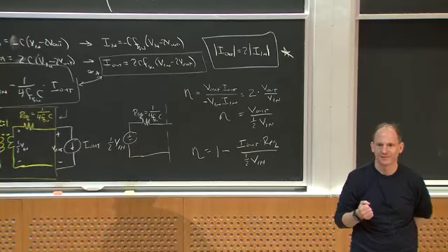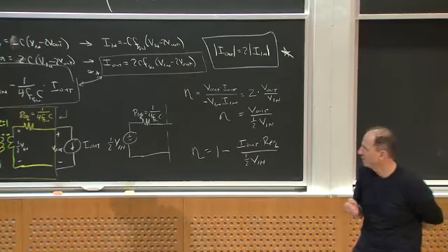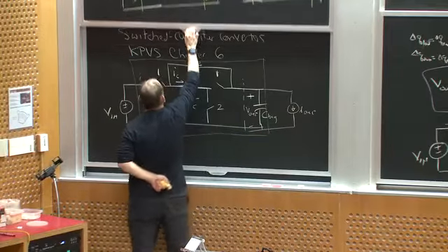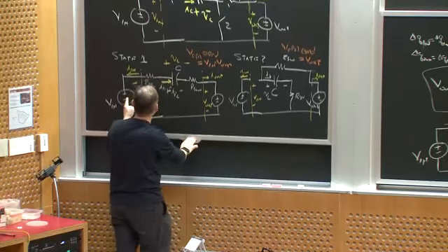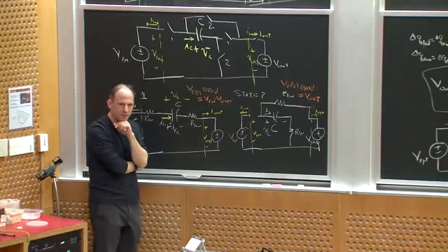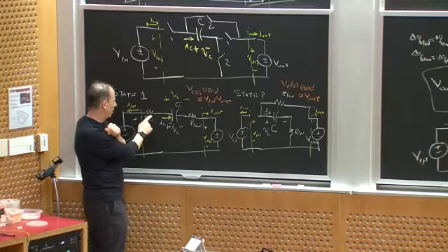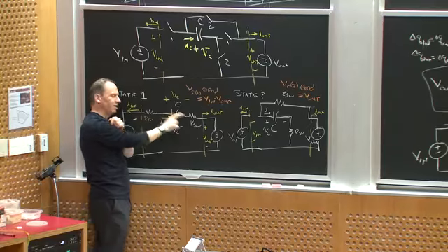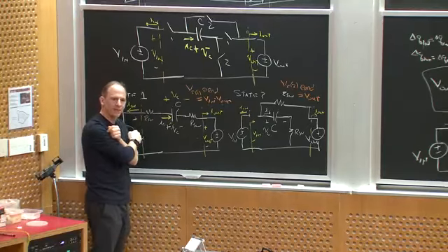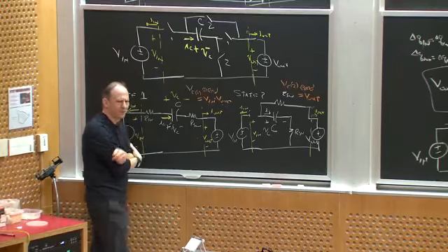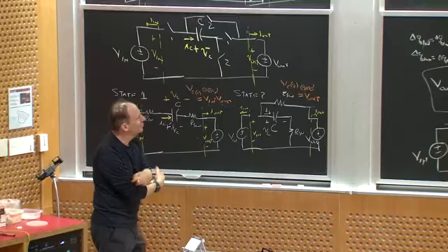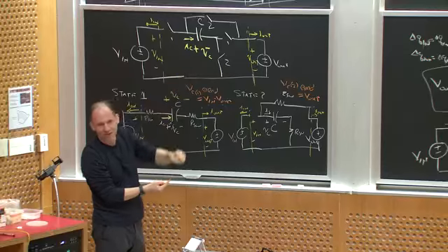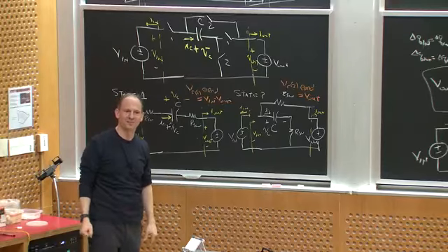Could you say it again, like where the power is being dissipated? The power is being dissipated in any parasitic resistance in the charge and discharge path, okay? So if I turn the switch on, it has some voltage drop across it, or if the capacitor has some parasitic resistance, it loses some energy in that. You say, well, what happens if I make my switch resistance go to 0? Well, all that happens is that the peak charging current gets higher, and it goes for a shorter time, and the total loss is the same thing. Okay, so mathematically it works out.